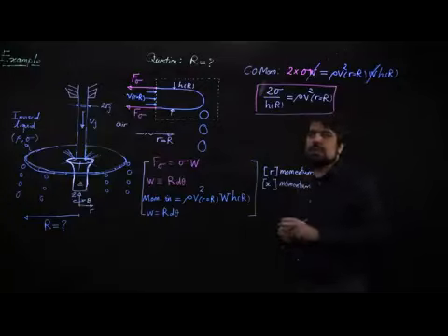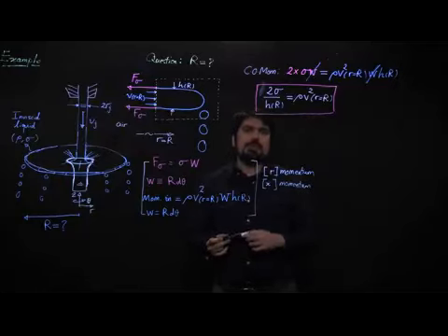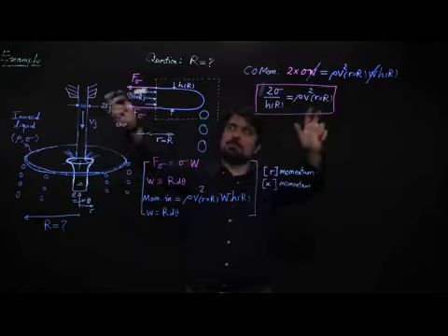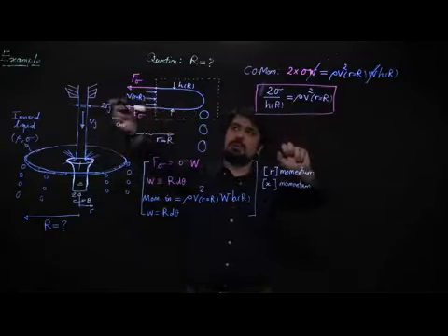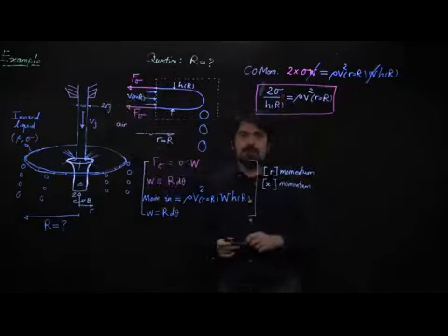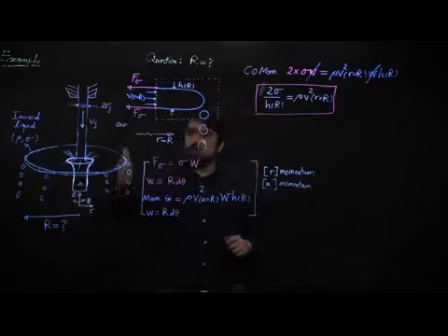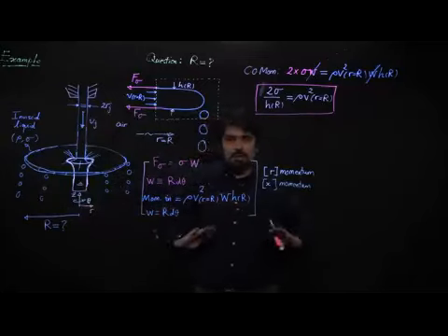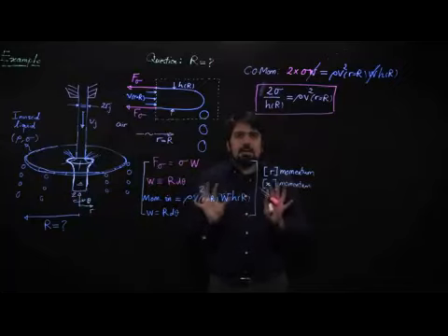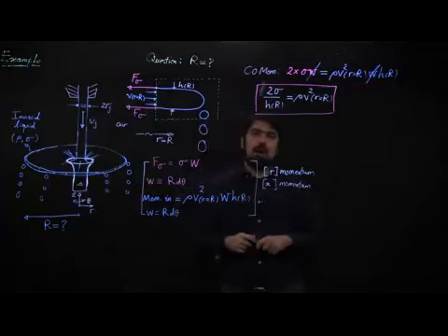So a very simple balance of force already gave us something very interesting, which is a relationship between the incoming momentum and a certain type of capillary stress that is resisting it. This is the pressure, the dynamic pressure that corresponds to the incoming momentum of fluid elements that enter the very edge of the liquid sheet. And this is the capillary pressure that is actually acting against it and is holding it. So really the balance of this liquid sheet is nothing other than inertia wanting to expand it further and further, and capillary putting a brake on it and holding that inertia at a certain equilibrium radial distance r.